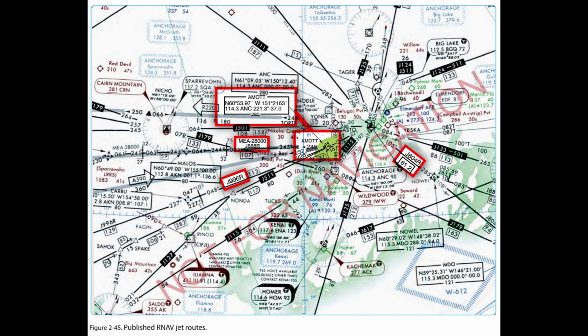The azimuth feature of VOR aids and the azimuth and distance (DME) features of VORTAC and TACAN aids are assigned certain frequency-protected areas of airspace that are intended for application to established airway and route use and to provide guidance for planning flights outside of established airways or routes. These areas of airspace are expressed in terms of cylindrical service volumes of specified dimensions called class limits or categories.